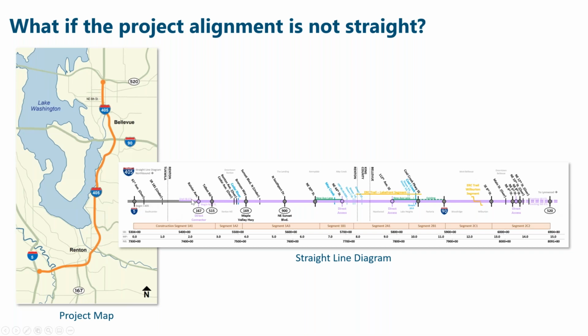And I've put all the crossings, all the different bridges that are going over this highway or under this highway, under crossings. And so using this diagram now, I can plot a linear schedule of our work relative to this alignment. And I have our stationing listed here. Our contractor has broken all the work into different construction segments. I've listed those here. So what I'm working on now is building a linear schedule for this project using this as my primary axis to plot the work.